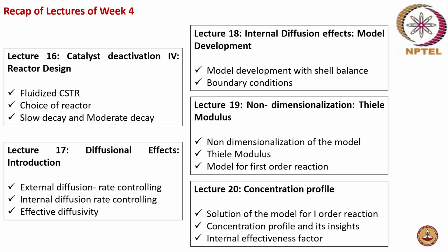So the internal effectiveness factor is nothing but the actual reaction rate that is happening, compared to the reaction rate when the reaction happens at the surface conditions. That is, when the inside of the pore is also at the same temperature and the same concentration of reactants as the surface, what would be the effective performance. That was introduced. Okay, are you there?